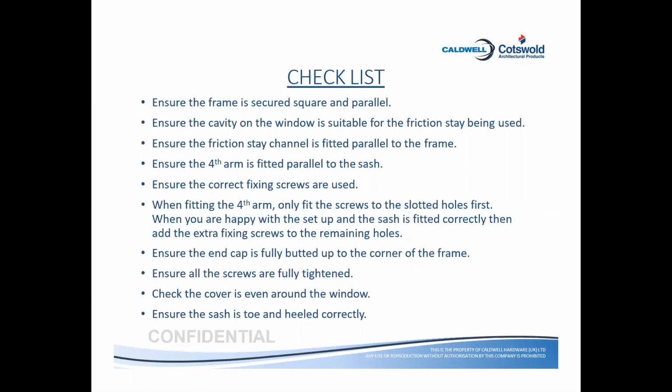Ensure that the frame is secured square and parallel. In fact, the window needs to be parallel to the earth, as well as positioned correctly. If the window is unfortunately not parallel to the earth or perpendicular to the outer, it will not perform.